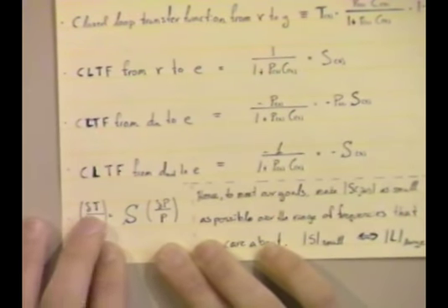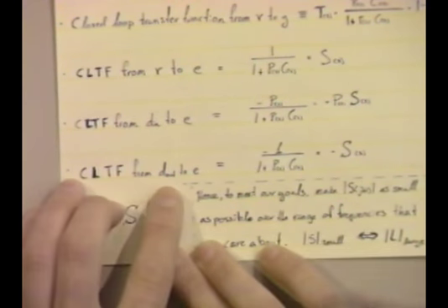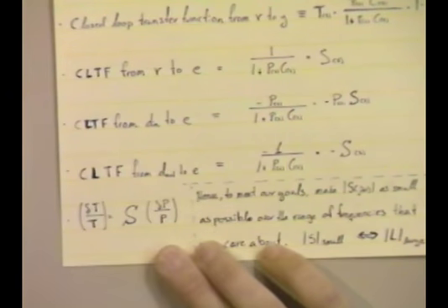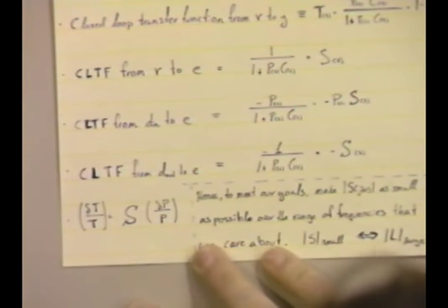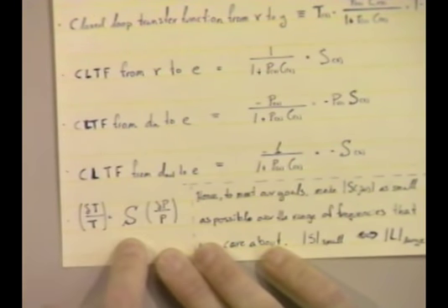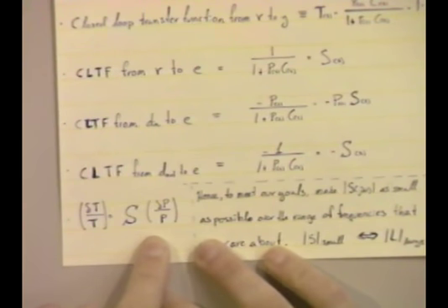And lastly, the closed loop transfer function from output disturbance to the error is given by the negative of the sensitivity. Okay? From all these transfer functions, and from the consideration that the fractional change in the closed loop gain is a fraction S of the fractional variations in the plant gain at some frequency, okay?